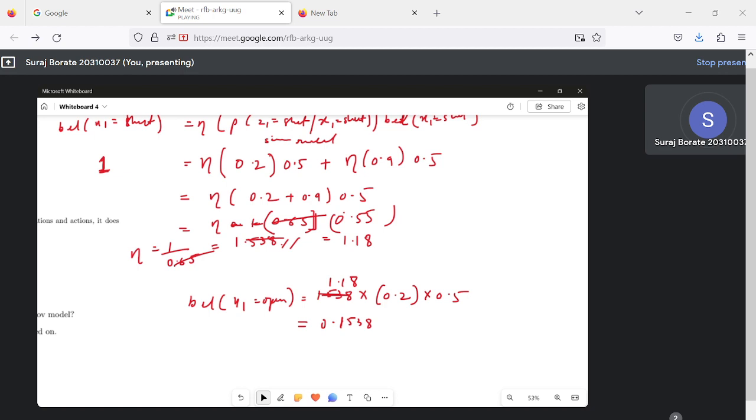Okay, so now we'll go through the entire procedure again. We started here with the Bayes filter algorithm, and it takes as input the belief at the previous state, the current input, and the measurement. And for all xt, or for all the states, first we do the prediction and then we correct our prediction using the sensor model.